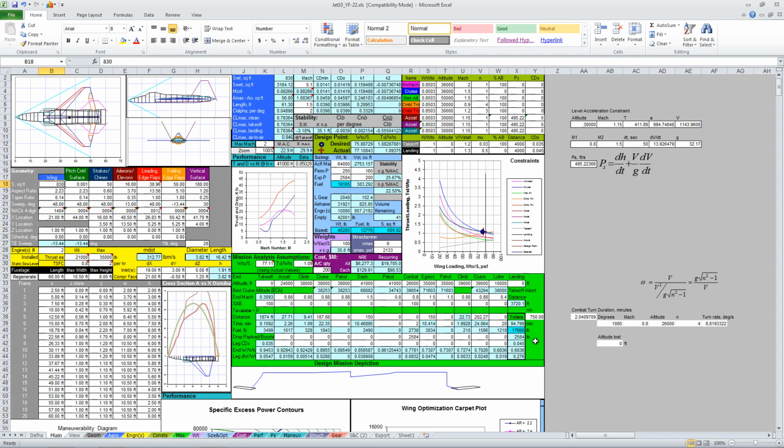Well, first off, now we have a lot of extra gas. We got rid of 1,100 pounds and we got rid of some drag, so the amount of fuel we have increased and the amount of fuel we need decreased. And the way the fuel increased is we specified an aircraft max takeoff gross weight. We only type numbers in the white boxes. The blue box is where we calculate how much fuel we carry.